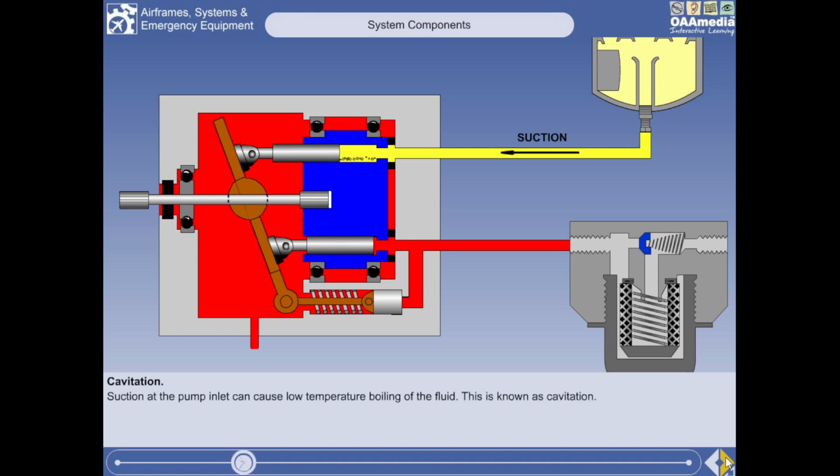When these bubbles pass through to the pressure side of the pump, they then implode with great force. This is known as cavitation, and if allowed to happen, it can cause severe damage to the pump. The sound of pumps operating while cavitating can range from a low-pitched steady knocking sound, like on a door, to a high-pitched and random crackling, similar to a metallic impact.